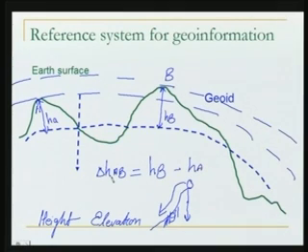Okay. Well, this is basically what we are doing. We are trying to find this delta HAB, which is nothing but the difference in heights of these two level surfaces or these two geoids which are passing through point A and point B. Also, this gives us that point B is at higher elevation, because if you put a water drop here, it will tend to flow towards A.